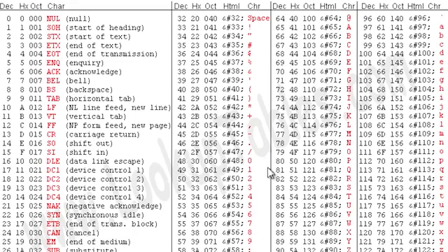So here's our problem. We're clearly sending a char, which is really a byte of data, but telling it it's an integer. It's different. So we need to handle the conversion on the Arduino end so that we print back out the right stuff. Let's go do that.